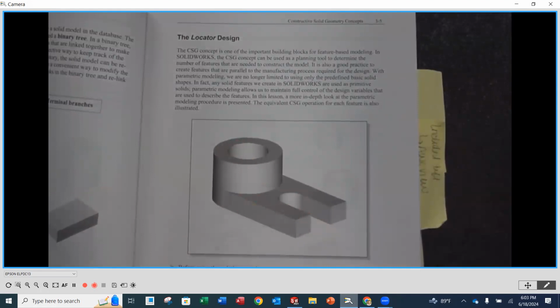You might say, well, why don't we do it where we look down at the sketch and we actually create this whole outer portion so that we don't have to create the slot in there. Again, I go back to, if we ever want to edit this, maybe we want to make a part that has no slot in there. Then all we have to do is delete a couple of features and my base is solid. If I don't have those individual features there, now I've got to go back to the sketch and actually completely edit it. It's going to be a little bit more work.